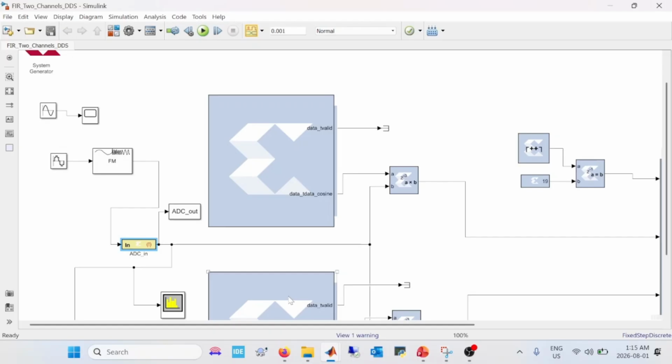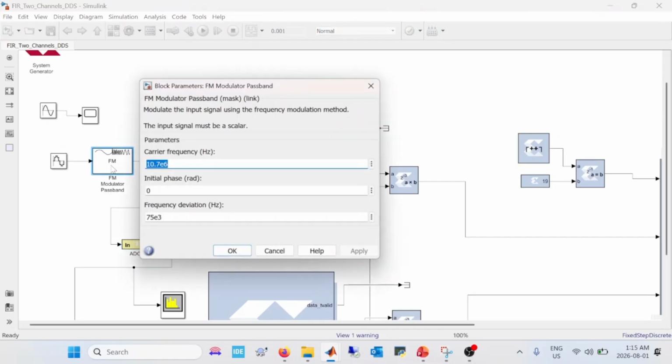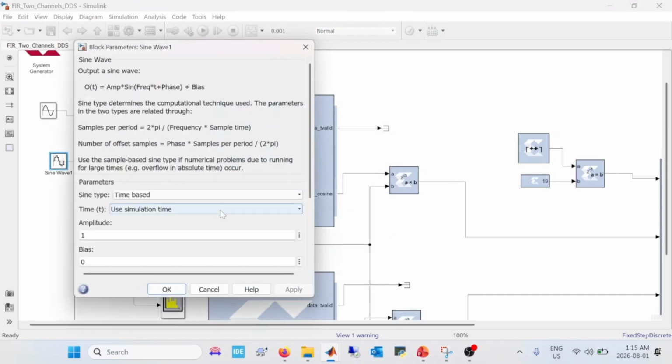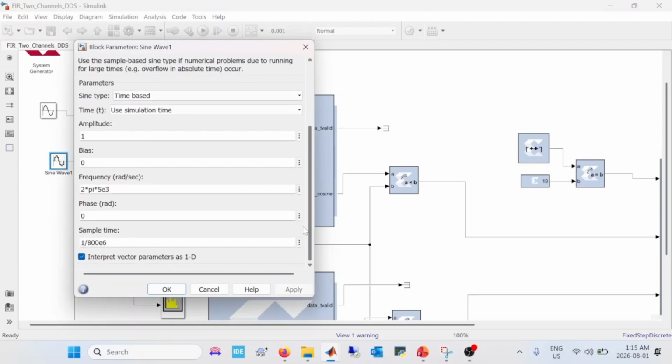It's going to be covered in the next videos, but for now I just want to focus on the bandpass sampling theorem, and I want to use this live demo to prove some key points here. I have an FM signal that's simulated. So let's see what we have here. We have 10.7 megahertz as a carrier frequency, a deviation of 75 kilohertz, and the message signal I believe is 5 kilohertz.